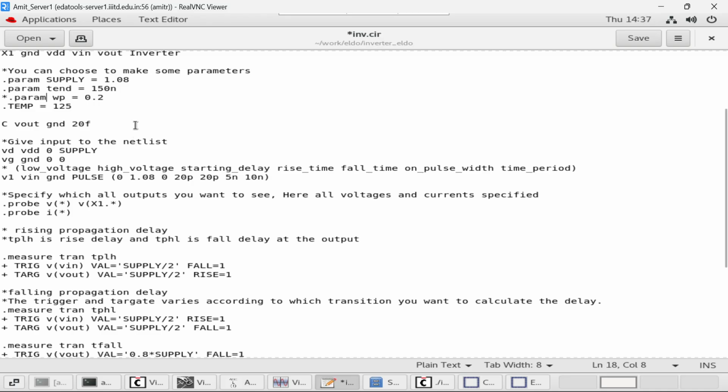Now we will supply the input stimuli to our instance that we have created from src.net. This is the signal name. The first name is the signal name. Okay? This VD means signal name, and this means pin name where this signal will be supplied. This is the pin name. This is the signal name, and this is the pin name where the signal will be supplied. Okay?